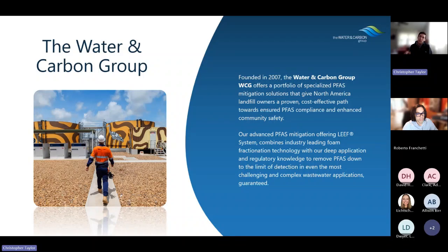This project in particular, in 2017, asked for the treatment of ammonia, TN, and then PFAS as well. In 2017, we had a response for ammonia and TN. I'm showing some SBRs along with an MBBR for TN removal. But the foam fractionation aspect, or I guess the PFAS removal aspect, is something that we didn't really have at that point in time.